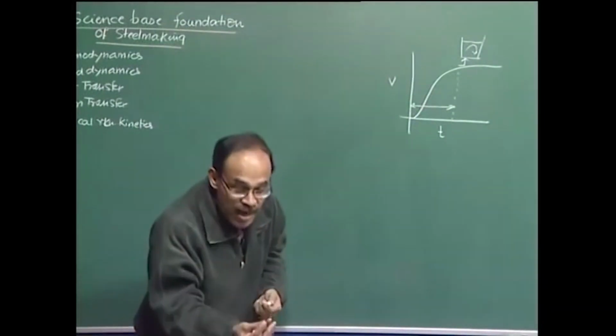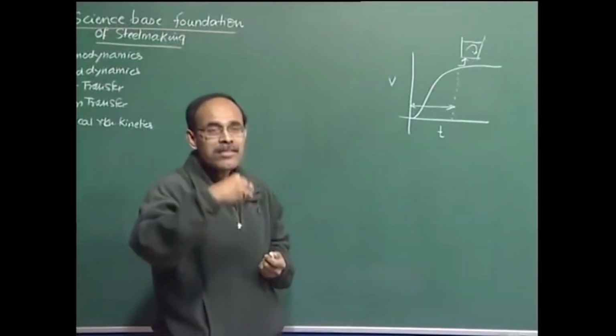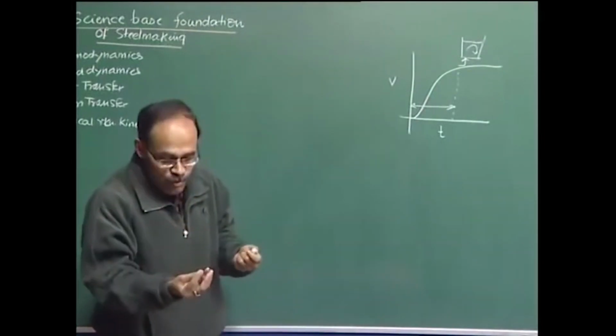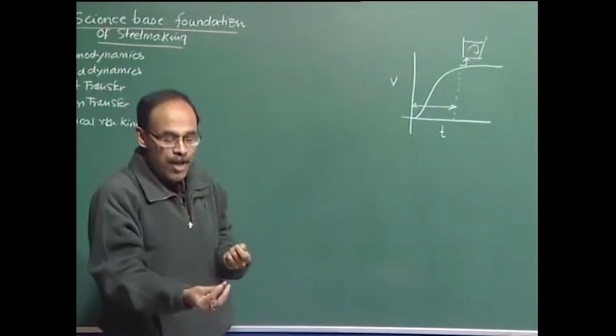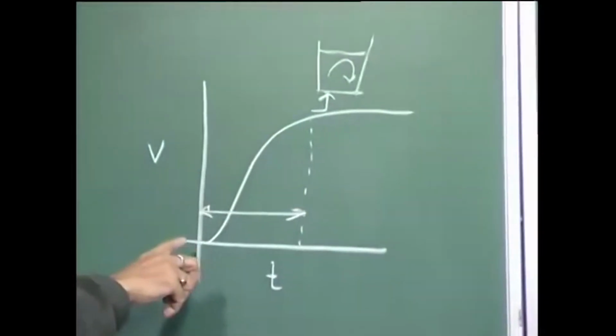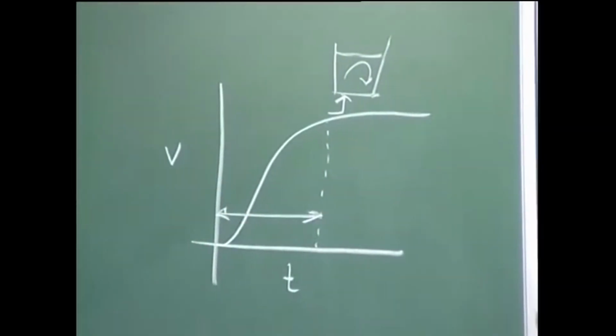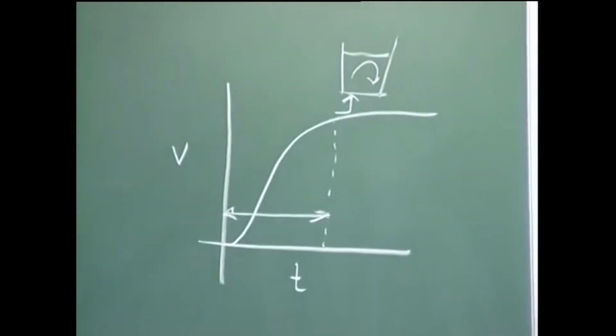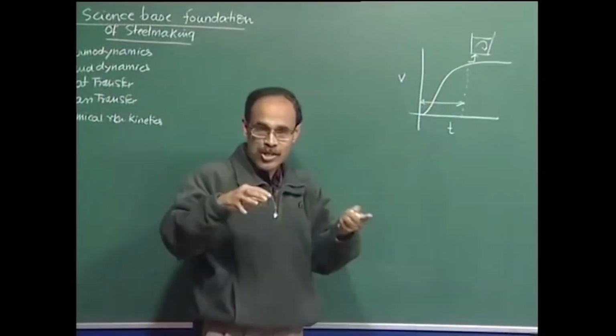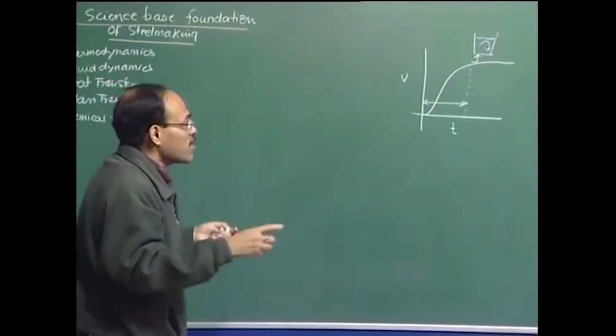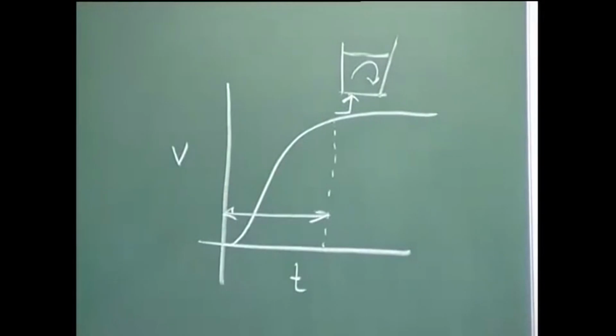That means, we have started to blow gas, and then for some time what happens is we have a power which is the buoyancy power which we input through the gas, and it accelerates the fluid, and at some point the energy supplied by the bubble is balanced by the losses through various mechanisms, and then we obtain a steady state process.